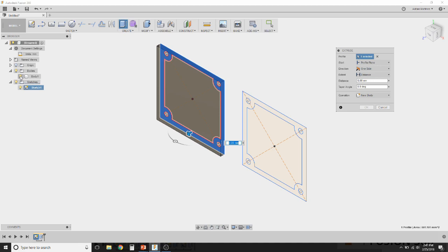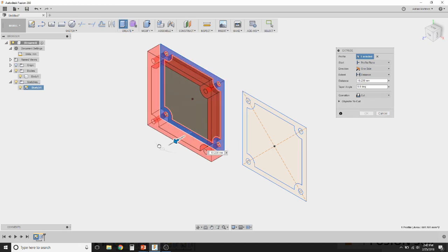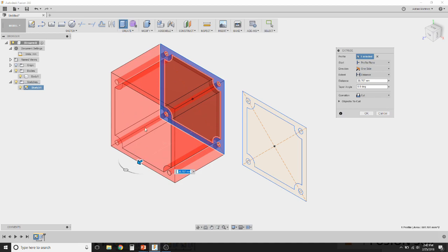We're going to talk a little bit about how the system behaves and how Fusion, in order to make the workflow for drawing easier, makes some inferences on what you want it to do. So I now have a sketch that I've selected to press pull through an object. If I grab the handlebars and pull it through, it generates this red box, which is indicating a cut function.